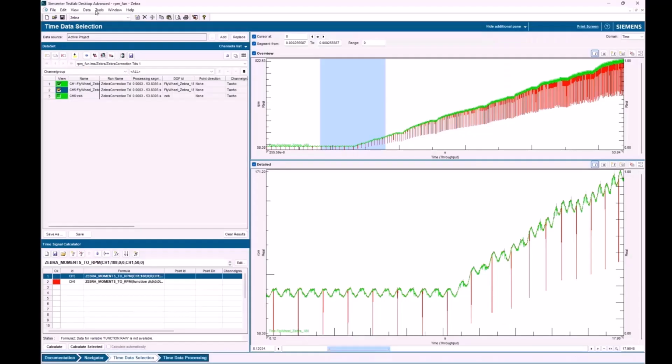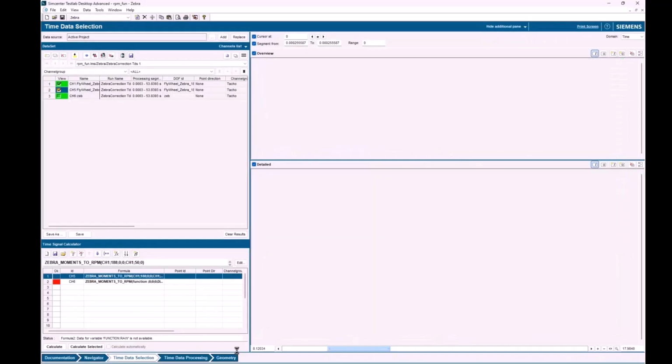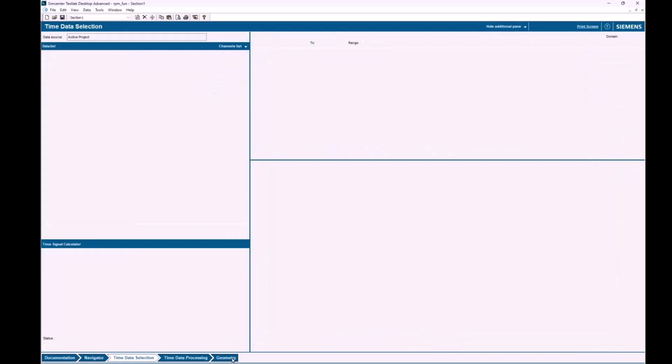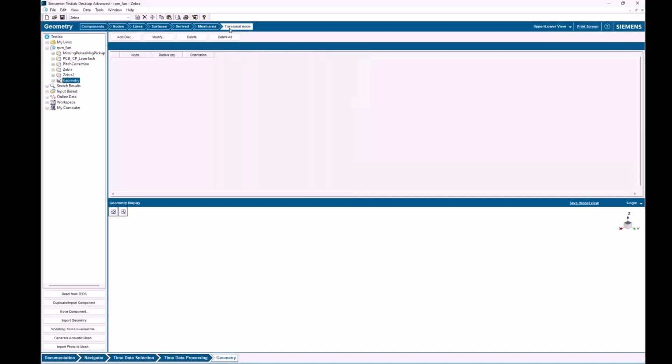That's very cool, actually. And that's a standard feature in the test lab geometry. And by the way, you can also use translational vibration. So you can have a combination of torsion and all the translational vibrations of your system. To create one of those pie-shaped wedges, it's with this torsional node. You just add a disc on a point here, and then it'll create that torsional node for you. So that's another option for things that you can build up and put in the geometry.